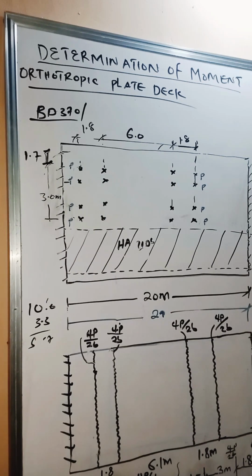load on the bridge. We have the live load according to the British standard BD 37/01. We'll have the HB load and the HA load being applied on this particular 20-meter span bridge deck. Right now, we want to calculate the maximum moment on the plate.